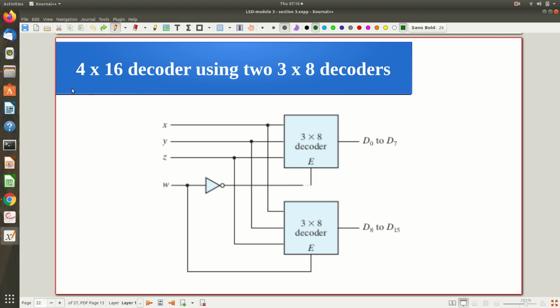Typically the coded information will be some n bit code, and this n bit code will be decoded to any of the 2 power n combinations, if all the 2 power n combinations are valid, otherwise accordingly. So this is the maximum size of a typical decoder. The original code may be binary, or something else also. Binary type of encoding and decoding is what we've seen so far.